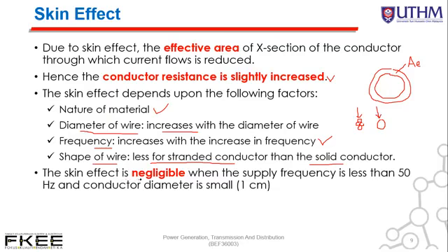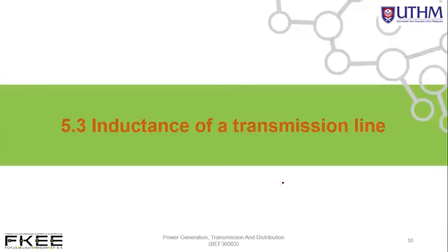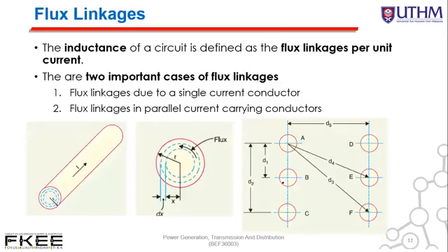And the skin effect is negligible when the supply frequency is less than 50 Hz and the conductor diameter is small, that is, less than 1 cm. Okay. Now we look at the case of inductance of a transmission line.